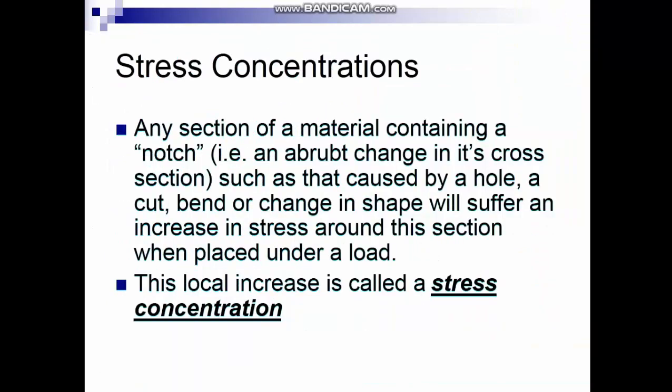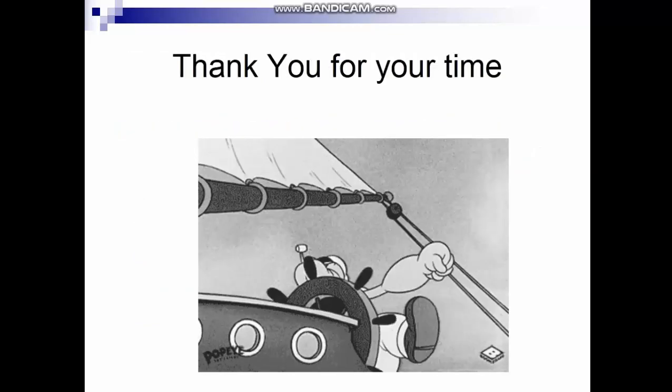So another thing is stress concentration. Any section or material containing a notch, such as a hole or cut or bend or change in shape, will suffer an increase of stress around the section when it is placed under a load.